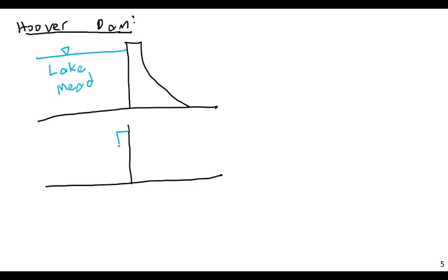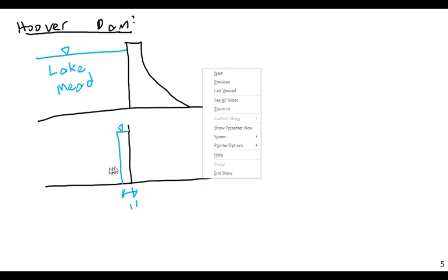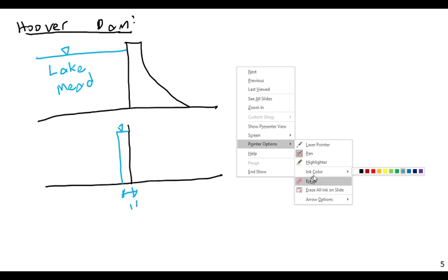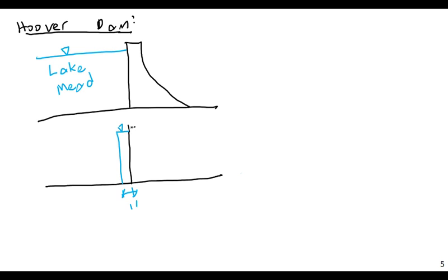Let's say I contain it, not a lake, but just 1 foot of water. How much dam will you need? If I only want to hold back 1 foot of water, how much dam would I need? Well, the answer, surprisingly enough, if you don't know fluid mechanics, is the same dam.